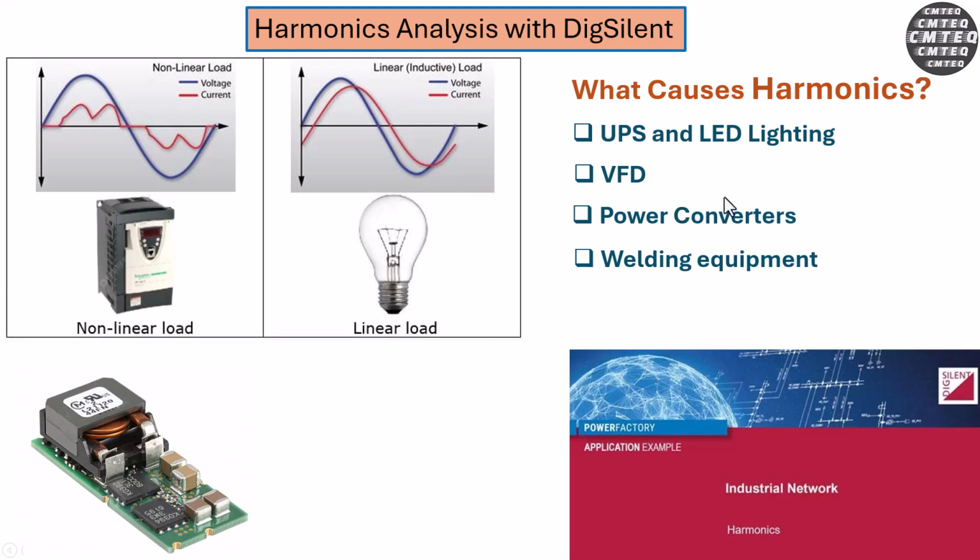But now, make no mistake, you've got power converters and controllers that basically have a power factor correction where the switching is controlled in a way that it tries to follow a sinusoidal waveform of the voltage so that it can minimize the harmonics, okay? So they are there, but still you're going to have systems that rely on switching converters that will have lots of harmonic distortion in the current that is going to be drawn.